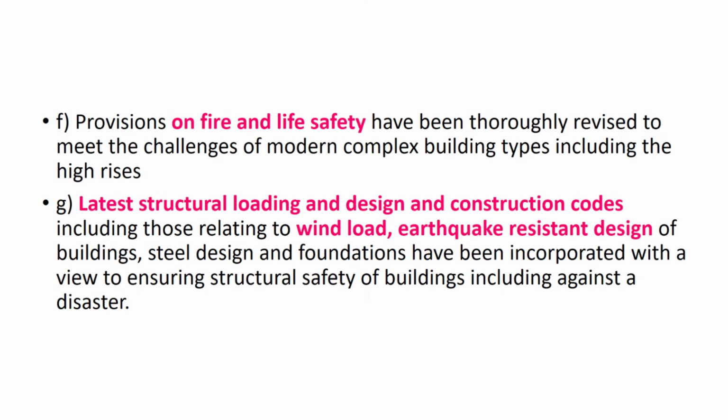Care should be taken to avoid use of damaged conduits or ducts. The end of that conduit shall be given suitable anti-corrosive treatment and holes blocked off by putties or caps to protect conduits from getting blocked. Now many times what happens during execution, the coupling is worn out, because labor काम करती है, lot of activities are there. वो निकलने के बाद वो conduit के अंदर में हो सकता है your concrete might go. So all conduit openings and junction box openings etc. shall be properly protected against entry of mortar or concrete during construction.